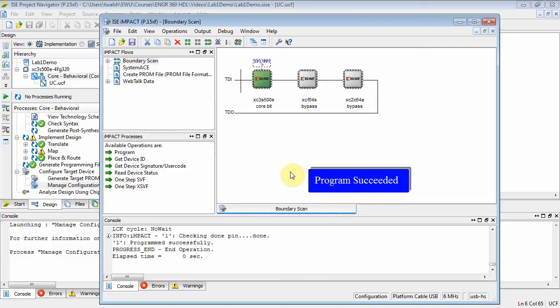Now you just go over to your board and you flip some switches and you verify that the 1-bit comparator is actually working. You'll flip switches 1 and 0 on the board. Call the instructor over, demo that, and you're good to go.